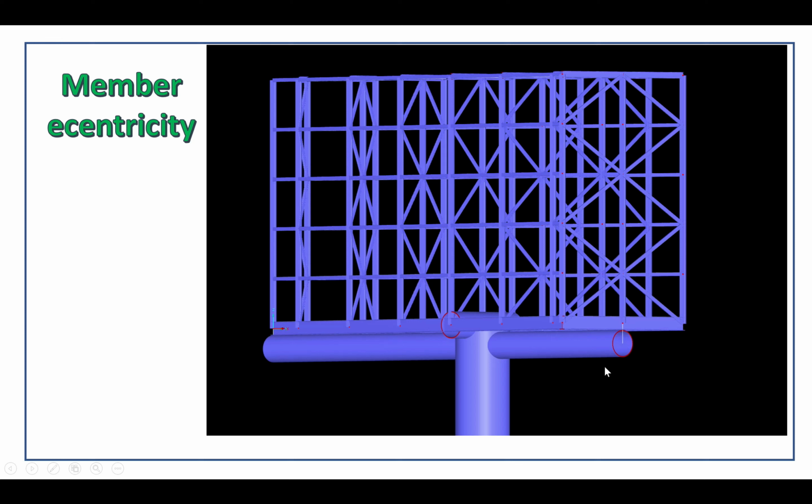Eccentricity will produce more torsion in your beam. You have to make sure your beam can resist this requirement. You have to make sure your structure is modeled correctly with the concept in the real construction. When you do not take eccentricity into account between the supported beam and the upper element, the force will apply at the center, so no extra torsion develops in this section.